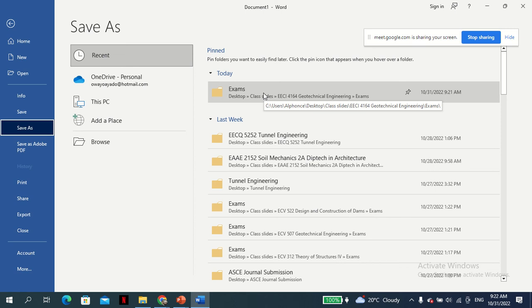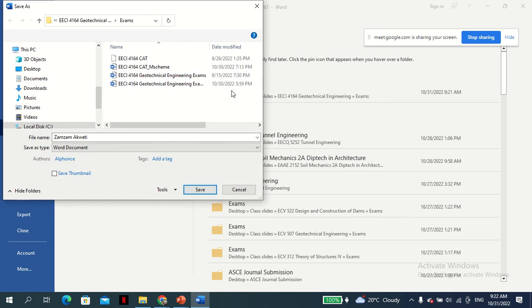You need to provide a way that it flows away. In literal terms, it means the water is under extremely high pressure, right? This is why it causes piping, and in a massive scale, it causes what is called liquefaction, with all the problems associated with it.